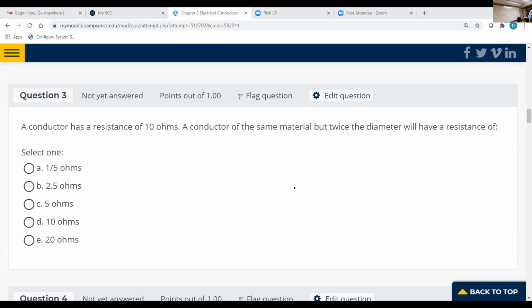Okay, I'm missing something. I've missed something. When you get to the CM, I understand the original one has 10 ohms. That's where you got your 10. But for the CM, how did you get the 1/4? Because you doubled with this. Yeah, when we doubled the diameter, when we went from 10 thousandths to 20 thousandths diameter, that caused the circular mils to quadruple. Gotcha.